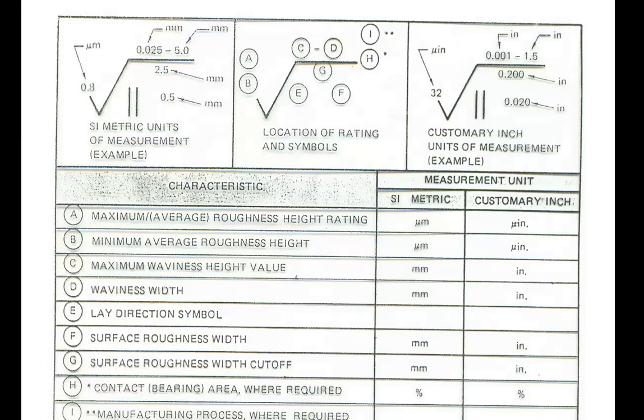It is the only number written in micrometer in an engineering drawing over a certain view: the roughness height. The unit of measurement in the first quadrant projection, in accordance with ISO, is micrometer. Roughness height is expressed and shown in micrometer.